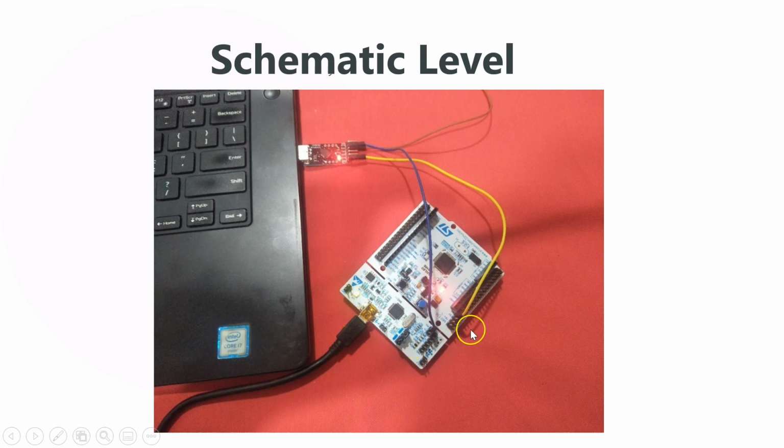In the past, microcontroller eval boards were very expensive, but with scale, the production costs have come down, and hence they're available for $10 or maybe $20 at max. And here, what I'm doing is, you have a USB to UART. There's a USB connection over here, and UART. So there are the breakout pins. Basically, you have TX, RX, and ground.